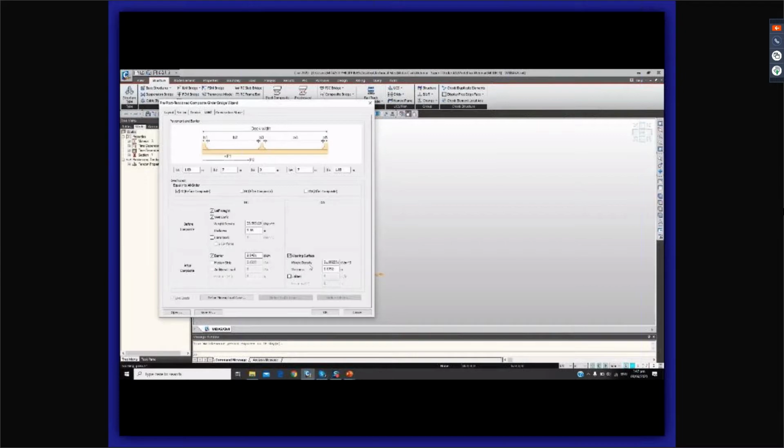And then for the wearing surface, here are the values of the weight density and the thickness of the wearing surface. And for the moving load cases, in order to activate the live loads, we first define the moving load cases. So check for the moving load code of Australia. Click on OK. Then check on the live loads.